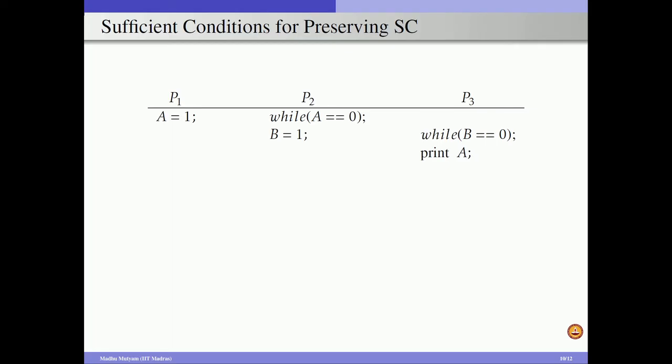Here we are assuming that an invalidation-based cache coherency protocol is used in our system. Also assume that the local caches in each of these processors initially hold some value a equal to 0. Now when we perform this store operation, we send an invalidation signal, but unfortunately it reaches only processor 2, and not processor 3, or core 3.